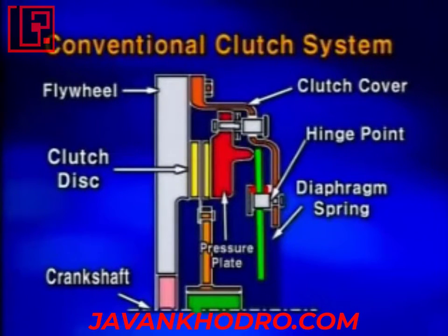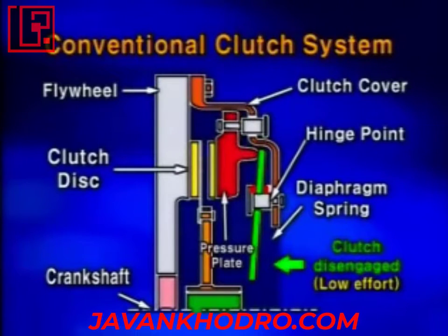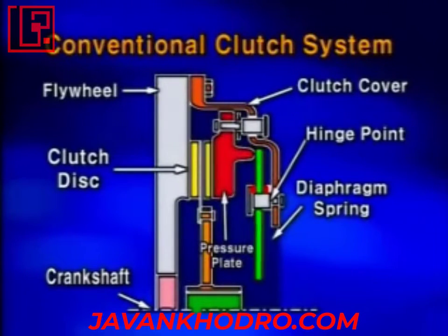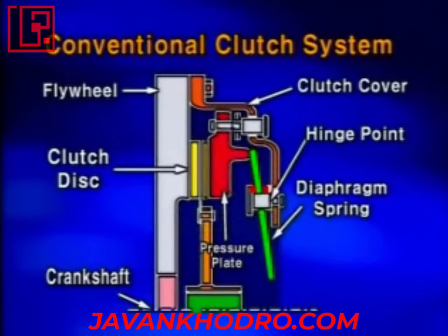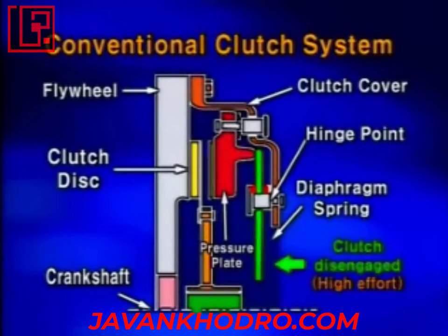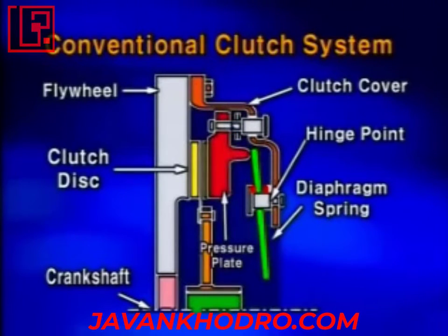For the conventional clutch structure, the diaphragm position varies to the fixed supporting point according to the wear of the clutch disc, so that the depressing effort for the clutch pedal varies. Therefore, the driver easily feels higher depressing effort of the clutch pedal during driving.